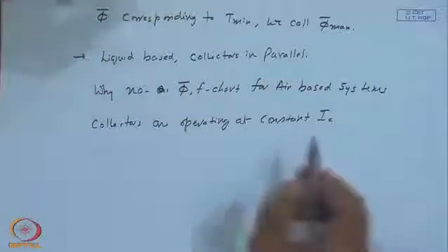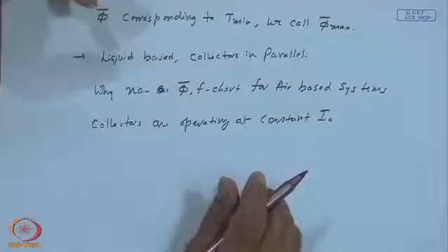Simply, if the ambient temperature average is, let us say, 15 degrees C, you may have the minimum to be 12 and maximum to be 18. So, if you calculate the critical level between 12 and 18, there will be good variation. Consequently, my utilizability may be different on different days, at least as far as the ambient temperature is concerned. However, the differences when averaged, once again, one may be an underestimate and the other may be an overestimate. Consequently, my phibar max corresponding to T A bar may be an acceptable number, but somebody can verify these things.